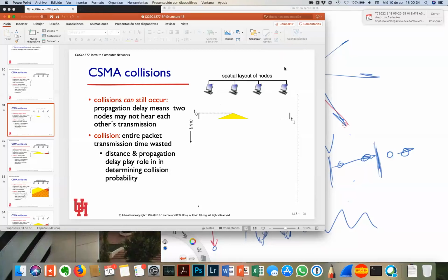So T1 is the time where we have another transmission. These 2 signals will combine to form a different electrical signal at that point where the yellow and the red meet. At that point, there's been a collision, but no one knows it yet. It's not like it travels at a different speed than the other stuff did. What happens is these 2 sine waves combine to form a new sine wave. No problem whatsoever with doing that.